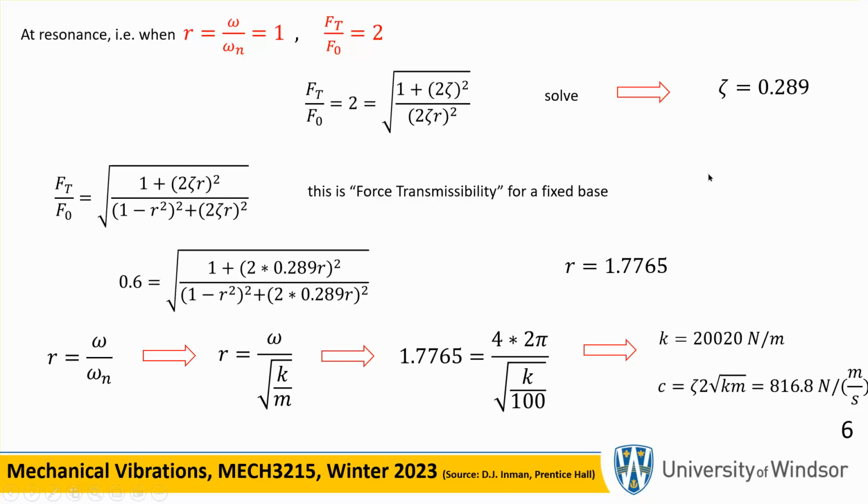So basically we designed a foundation or isolation system so that the requirements that we wanted were held, namely at 4 hertz the ground isolation, foundation isolation, was 0.4, or 40%. And at resonance, the maximum transmitted force ratio Ft over F naught was 2.